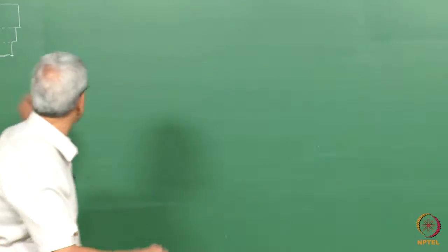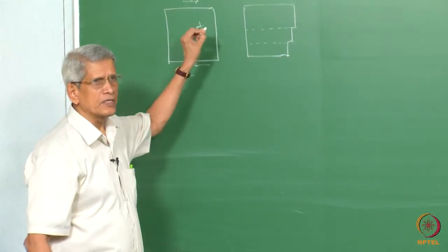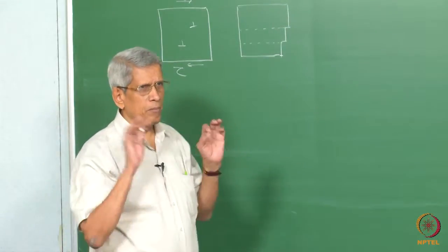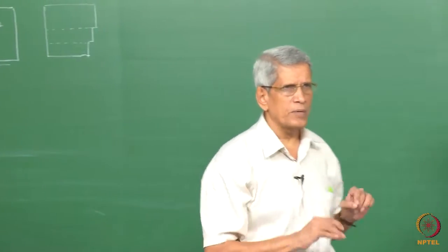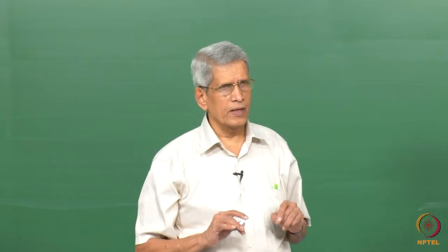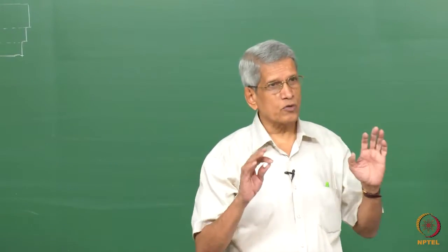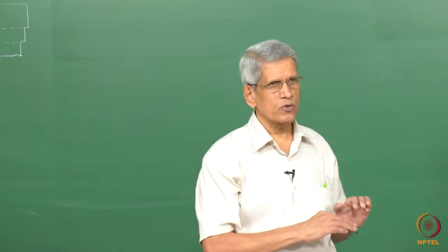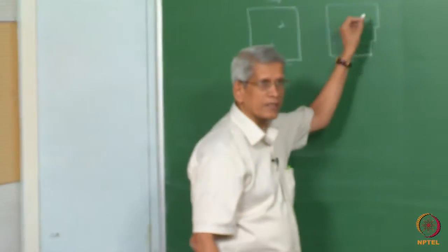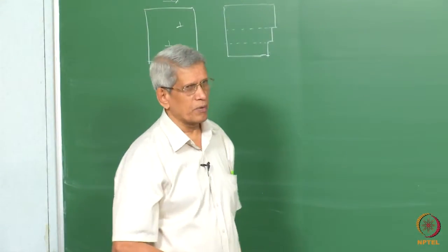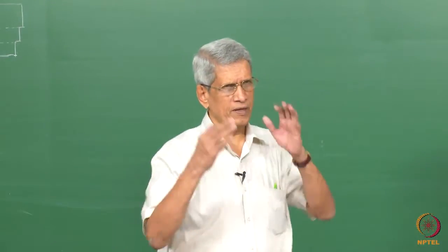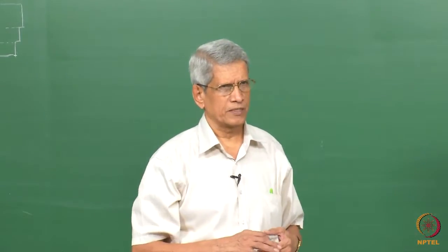And the dislocations may be uniformly distributed at so many regions. So, macroscopically it appears to have homogeneous deformation, but microscopically the deformation is still inhomogeneous. Macroscopically it appears homogeneous. Microscopically, when you look at it, from this region nothing has happened, this region nothing has happened. So, it is inhomogeneous deformation. That is what gives rise to an appearance which is macroscopically, because of the resolution at which we look at it, homogeneous.